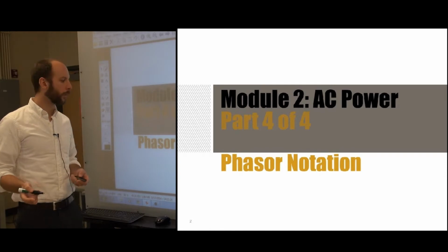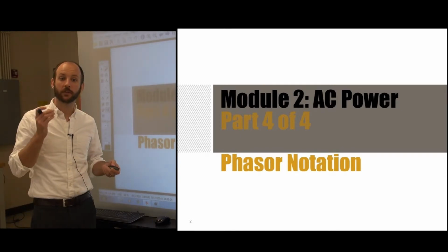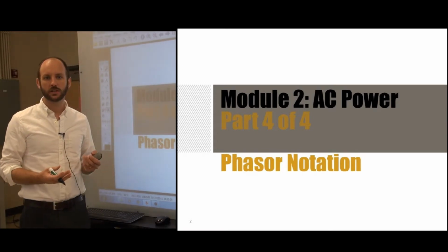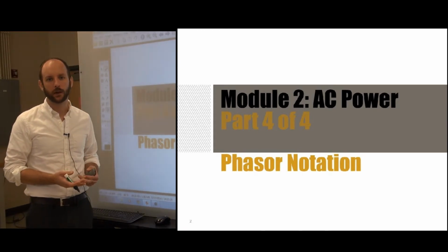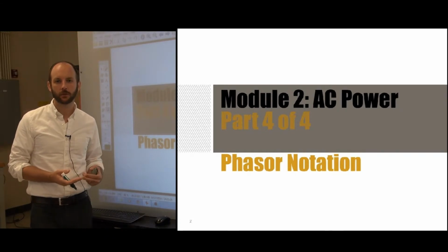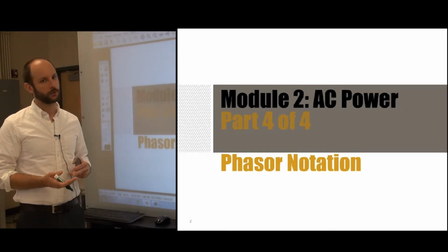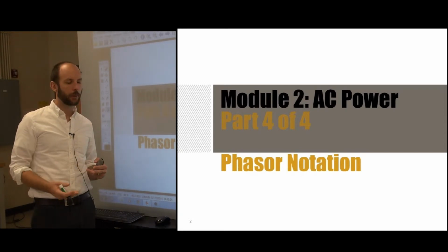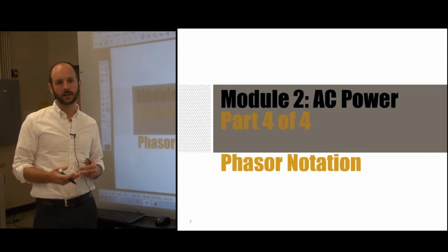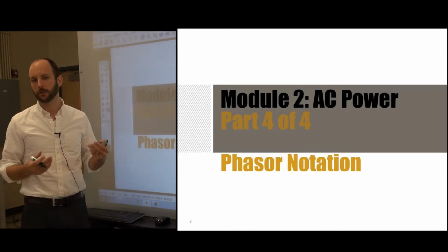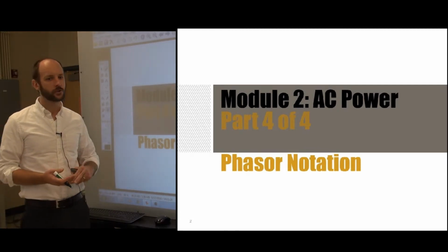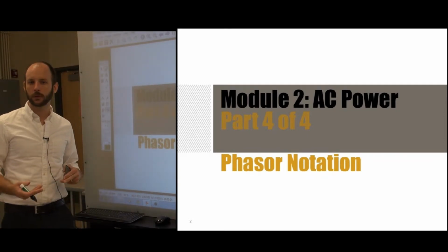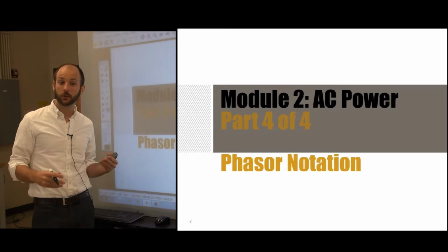It's also important for us to know what the RMS value doesn't tell us about the sinusoidal quantity, which is the information regarding the timing of the sine function. When we know the RMS value, we don't have any information about the frequency of the wave or about the phase of the wave. In most power systems applications, frequency is taken as a constant across the system. For example, we've been talking a lot about the national frequency in the United States being 60 hertz and in most European countries being 50 hertz. That's constant across the system.